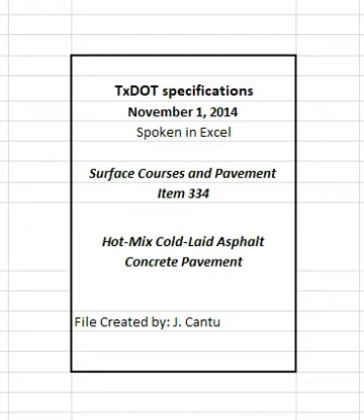Begin rolling at the low side on super elevated curves and progress toward the high side unless otherwise directed. Avoid displacement of the mixture. Correct any displacement that may occur to the satisfaction of the engineer. Ensure pavement is fully compacted before allowing rollers to stand on the pavement.